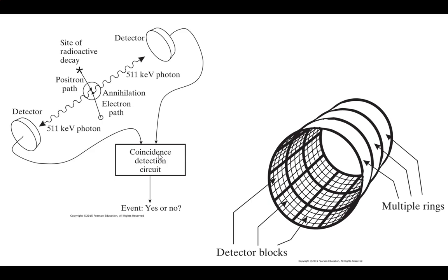So this is why we say it's got to be in the picosecond range, right? If it's not at least 100 picoseconds, now I'm getting you down at technically around 80 picoseconds. You're at about an inch. So you really ideally want tens of picoseconds. That's the sweet spot where things start working out. I therefore need something very fast.